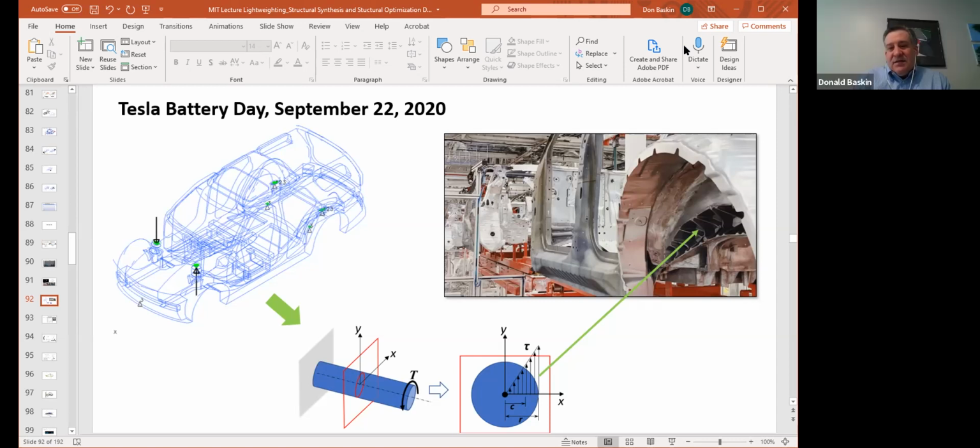And to be honest, most customers will notice that long before they notice torsional stiffness. Torsional stiffness is more for the fringe lunatic car enthusiast who goes around corners fast, or maybe even tracks their car. It's not so much about driving down the road and hitting bumps. Most customers notice a car is quiet and comfortable, has good so-called noise vibration harshness, NVH, when it has a high bending stiffness. That's a good point. Anyway, good question. Really excited to see if they're able to do that.